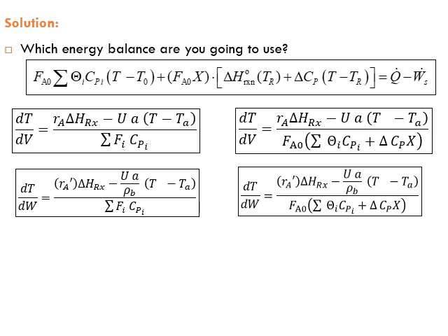Can we use this equation? Well, this equation is valid, but it's difficult to solve for T because of the complexity we have here. So which one are we going to use? It's a single reaction, so we're going to use the equations written in terms of X. And we are designing a plug flow reactor, so we're going to use this equation.